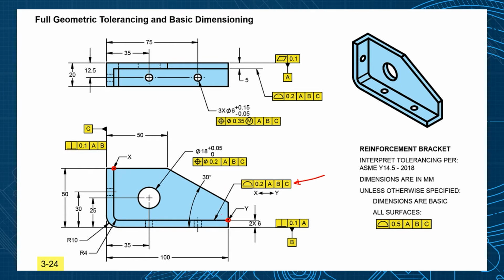Now this is really important to show that arrow again, because there's multiple ways to go from x to y. You can go x to y along this northern route here. We can go x to y around the bottom, or we can do x to y through the middle. And that's why that arrow really clarifies which side of x to y we're controlling, from here all the way to here. So that's going to create an offset tolerance zone, half of that 0.1 millimeters on one side and 0.1 millimeters on the other side. Now the actual surface has to be cut inside that tolerance zone.